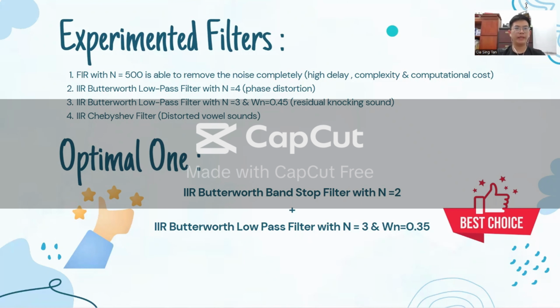In this assignment, we experimented with different types of filters, like FIR with 500 orders, but it has a higher delay, and we also tried different orders and different cutoff frequencies. We also tried the Chebyshev type of filter. Hence, the optimal one that we chose is the IIR Butterworth bandstop filter of second order, combined with the low-pass filter of third order, and the cutoff frequency is 0.35.